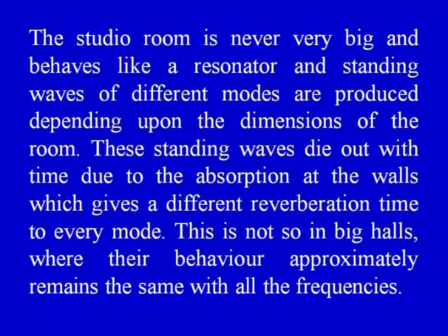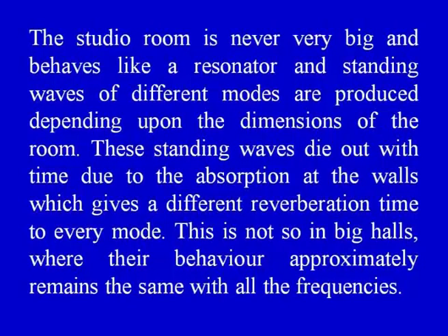The studio room is never very big and behaves like a resonator, and standing waves of different modes are produced depending upon the dimensions of the room. These standing waves die out with time due to the absorption at the walls, which gives a different reverberation time to every mode. You see, this is not so in big halls, where their behavior approximately remains the same with all the frequencies.